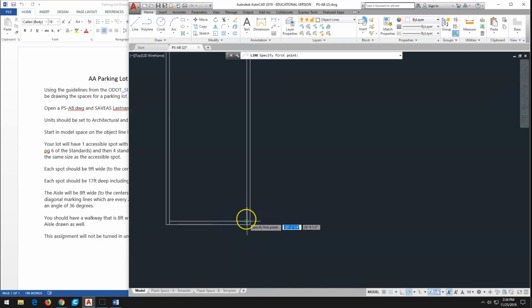and I just want it to be somewhere under the 2 foot mark, or right at the 2 foot mark from the bottom. So I will go up, and I'm going to put it in at 1 point, or actually, sorry, I want to put it in at 1 foot 6 inches, just so that it's under that 2 foot mark. And then I'm going to draw it, actually I'm just going to draw it as a construction line here.